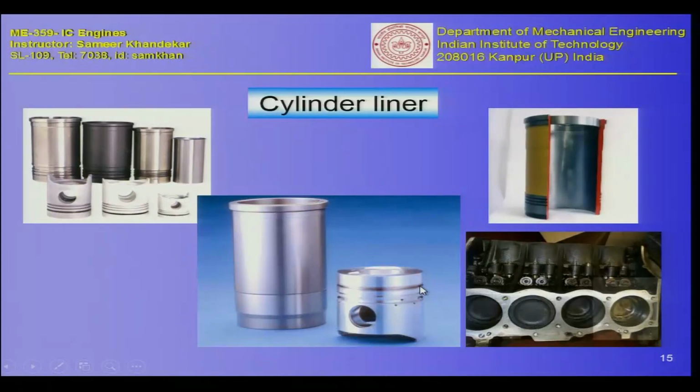for piston rings. So the piston rings will be inserted here, the oil rings will be inserted here. You can see some small holes for the oil to come out. So oil rings will be inserted here, the connecting rod will go here, and this particular assembly will be now pushed inside this cylinder liner, and essentially the piston will go in reciprocating motion inside this liner.